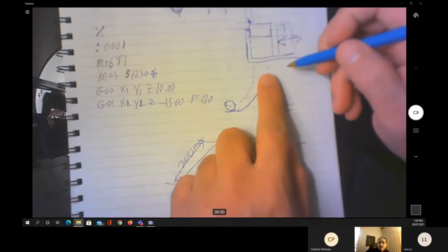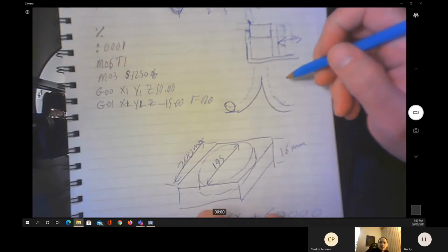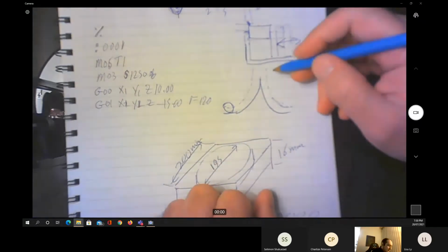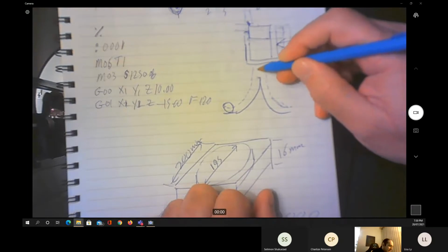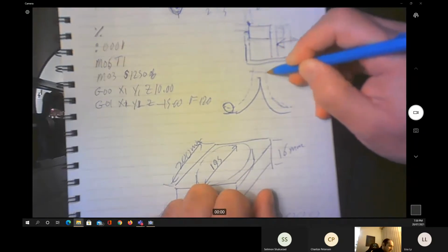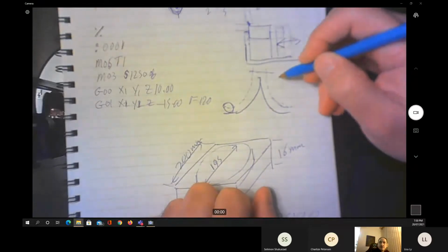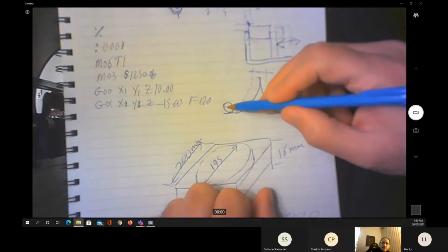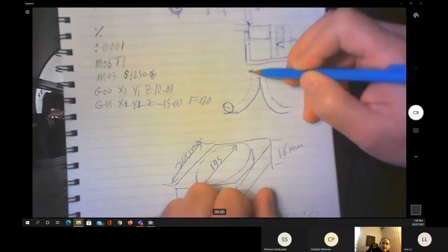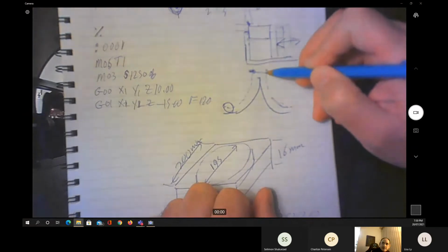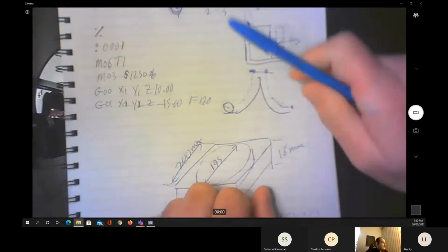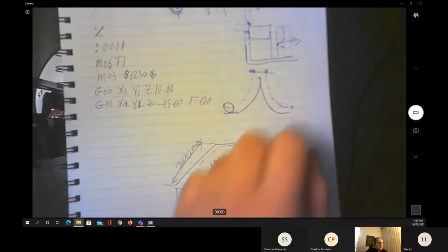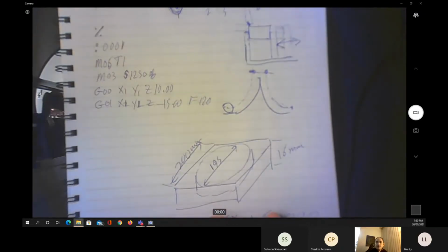Now you can see that these lines are not going to be connected at all. So what I'm going to do is measure something from here to the offset by the radius of my cutting tool, and make a horizontal line. So my cutting tool will move from here to here, then move horizontally to here before it continues doing the G03 to the final position.